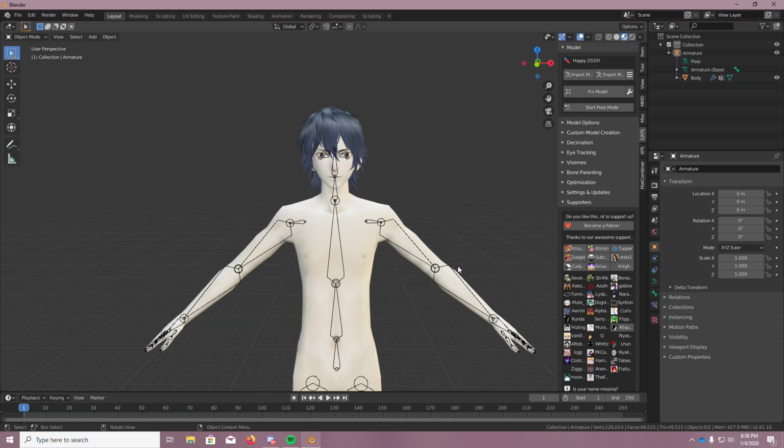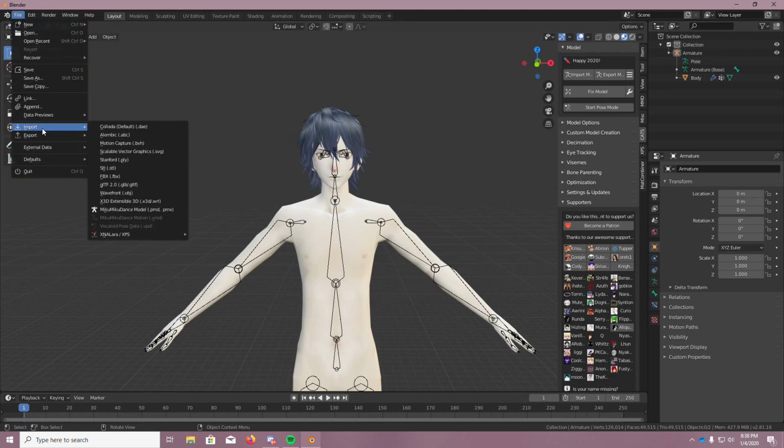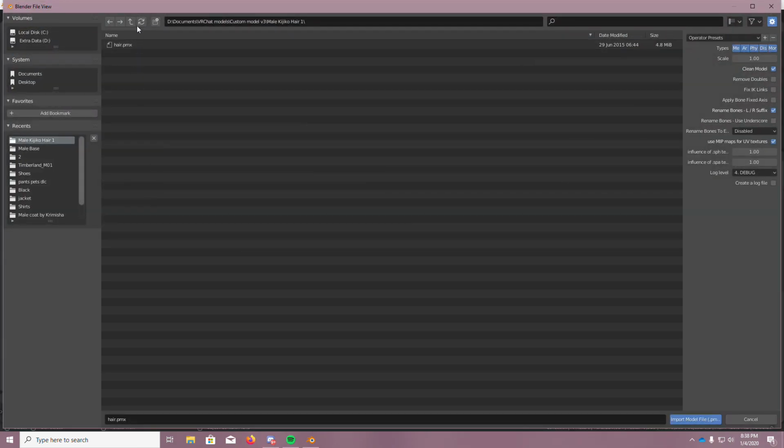So generally the principle is exactly the same. You just gotta position where you want the mesh to be, and then you join the mesh, and you position the bones a bit so they're close enough to be merged. You then merge the mesh, then you merge the bone armatures, and then you fix them all. So now let's continue and add more clothes.